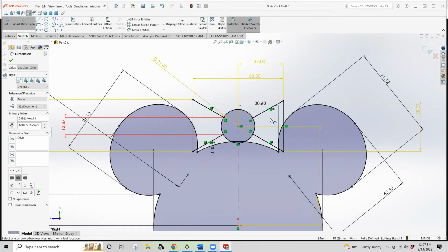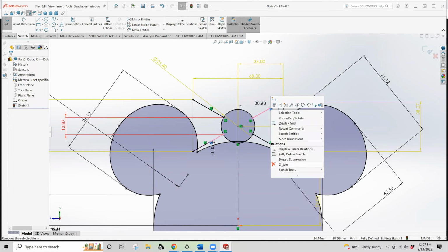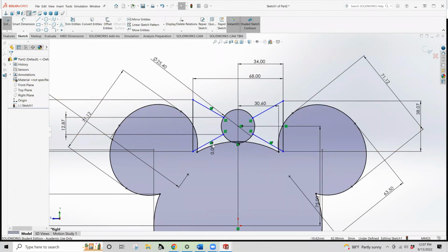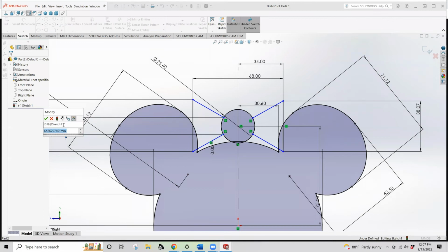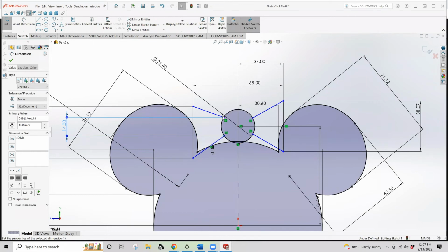So that I have to step out of the Smart Dimension tool. And if I delete that collinear relationship by right-clicking, sometimes you'll have to do that in order to make a change. If I did that and now set this to be 14, by breaking that relationship, I can now change the angle of the one relative to the other, so the types of relationships between those lines is important, and it also factors into whether or not you can get something to full definition.